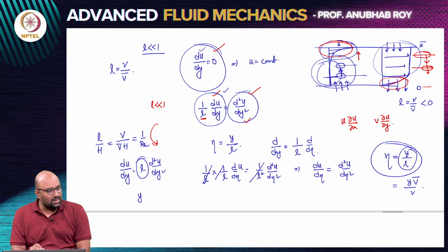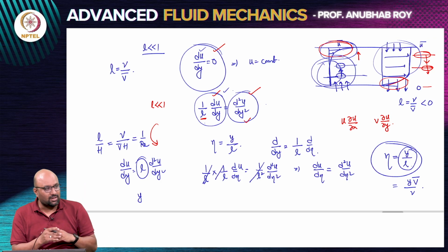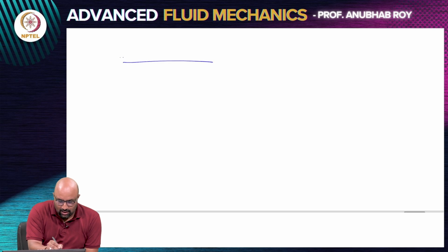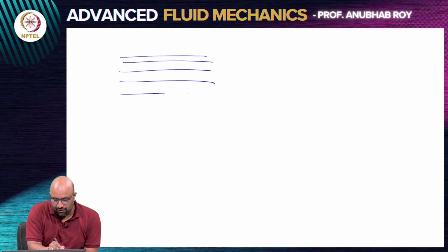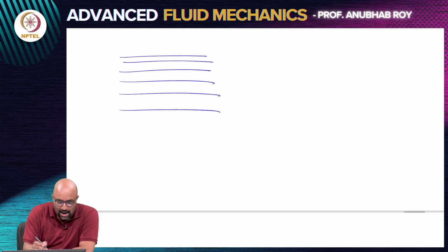Now, the acceleration here is not responsible for the velocity changing in x, but there is a vertical transport that is there. So instead of thinking of it as an acceleration, you can rather think of it as a momentum transport. That I have different layers of fluid, each moving with different velocities. So when you think of a shear flow, if you go back to this picture of slabs, fluid is basically broken into slabs, and you say that each of these slabs is moving with different velocities. If you have this kind of a cartoon.